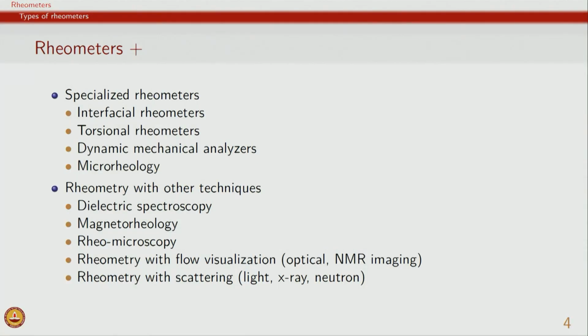If you see that the dipoles are also getting slowed down, then you know that whichever has dipoles is the one which is slowing down. But if you see that there is mechanically things are slowing down, but dielectric it does not slow down, then you know that the other component is probably responsible for the overall mobility decrease in the material. So, therefore, you can complement and do dielectric spectroscopy and rheology together.